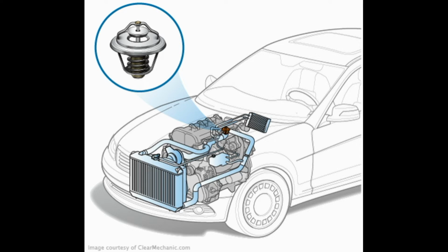4. Coolant temperature sensor. As the name suggests, it is a temperature sensing device in the engine cooling system and it monitors the engine temperature. It provides the data required to control the operation of the radiator fan. The engine temperature display at the driver's console gives a reading according to the data provided by the coolant temperature sensor. Further, in ECU-controlled vehicles, its data is used to optimize the fuel injection and ignition timings of the engine for better performance of the vehicle.